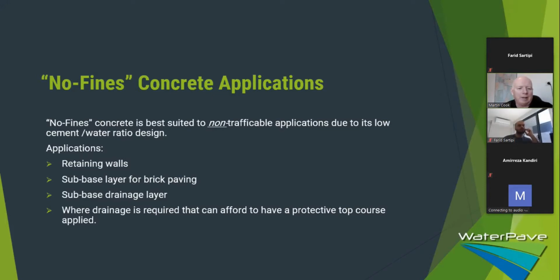It's used as a sub-base for brick paving. So you put that down first and put some brick paving over the top of it. You keep the gaps a little bit wider and the water can pass through that with a nice hard-wearing surface. It's also used as a sub-base drainage layer, wherever drainage is required and they can afford to have a protective top layer over the top of it.